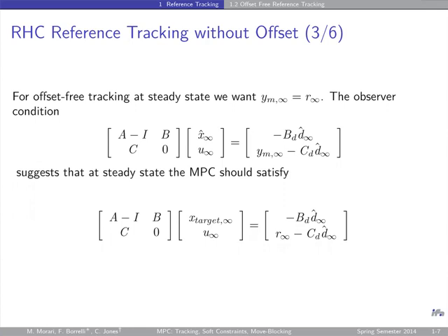Okay, the output constraints also exist, but they're usually not hard. There's some maximum pressure, but as long as you're not too long at the maximum pressure, it's okay. You can violate it a little bit, but not too much. Or you may have some current limitation. Is there a hard limit? No, a little bit higher current is okay. So on those output or state constraints, usually they are not hard, because you cannot guarantee it anyway, even with whatever control system, that they are satisfied exactly. You don't know the model exactly, so you don't know exactly what's allowed as an input to keep that output within constraints.